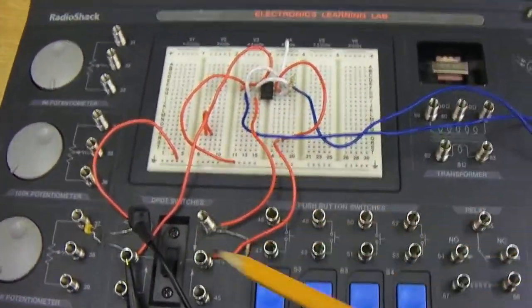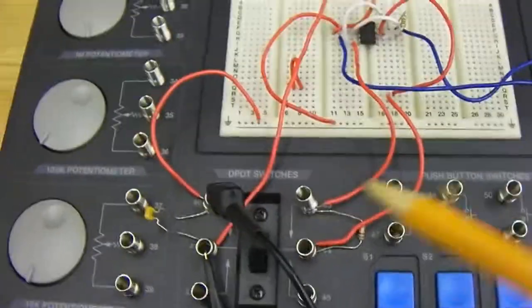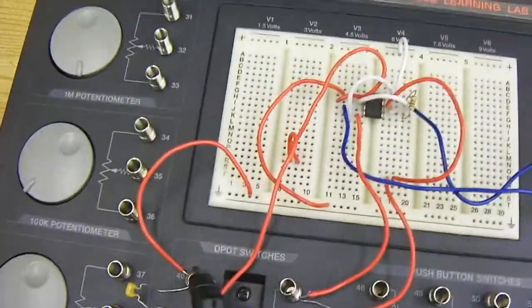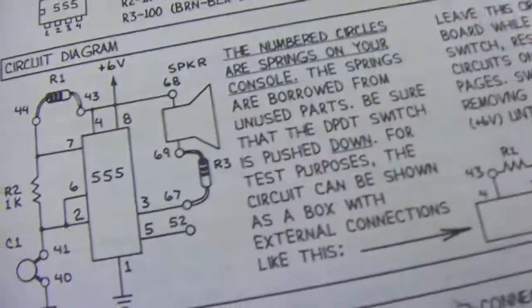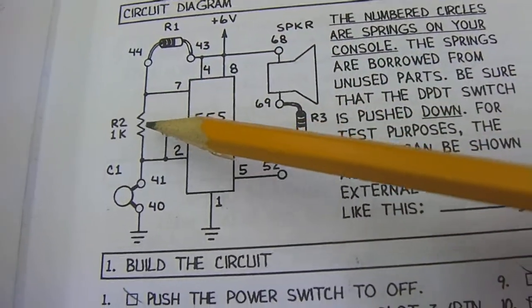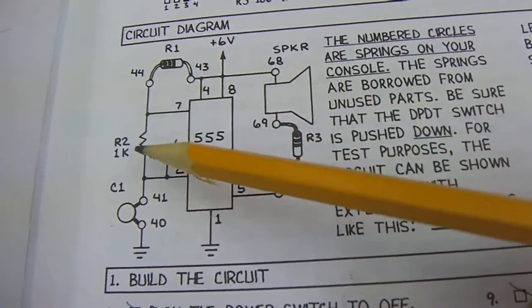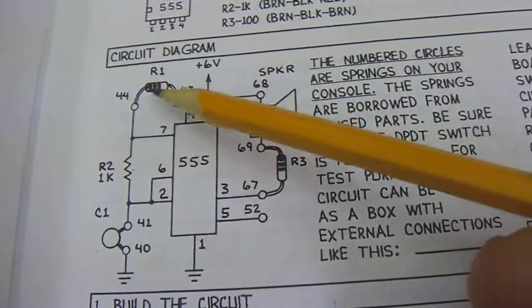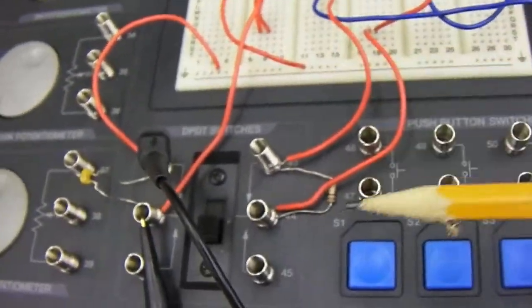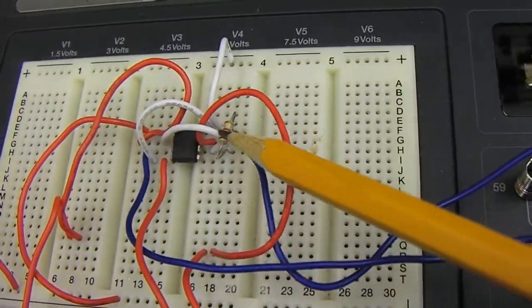Now we'd like to look at the timing of the waveform. Our circuit here is generating that waveform, and the timing is based on the value of this capacitor, which is called C1 in the circuit. Here's the schematic diagram of that circuit. Here's C1, capacitor 1, and then we also have two other components involved in timing, resistors R1 and R2. One of those is right here, and the other one is on the breadboard up here.